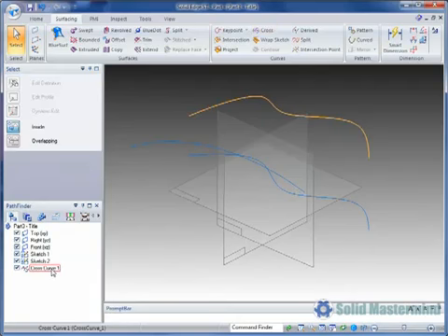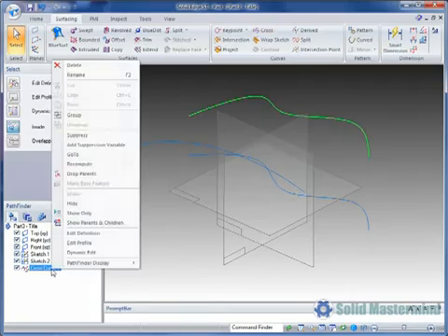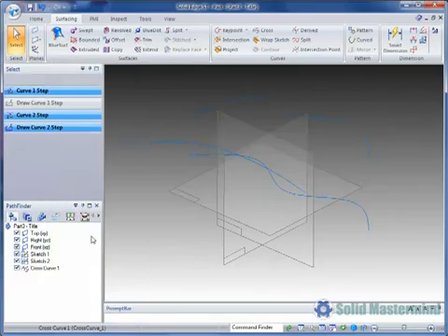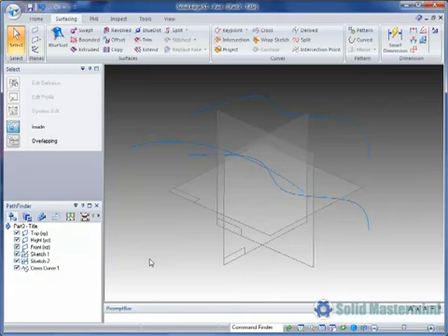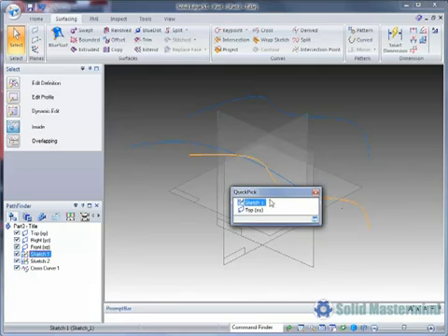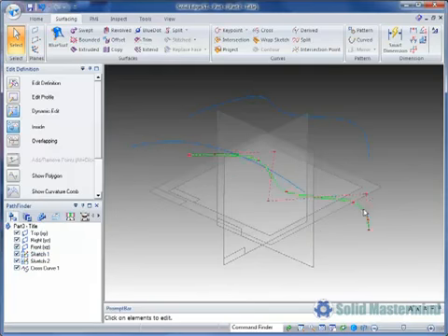Once created, a cross curve will appear as a feature in the Pathfinder. From here it can be edited like any other parametric feature. However, to modify its shape, we simply need to edit its underlying sketches. We'll double-click on the curve in Sketch 1, then drag one of its control vertices to modify it as shown.